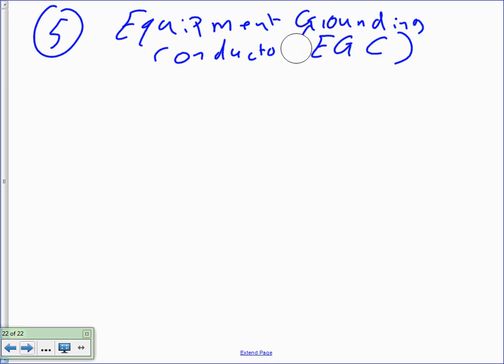You put the brackets here, you confuse. For the equipment grounding conductor, your reference is going to be 250.122, section and table. A piece of cake.